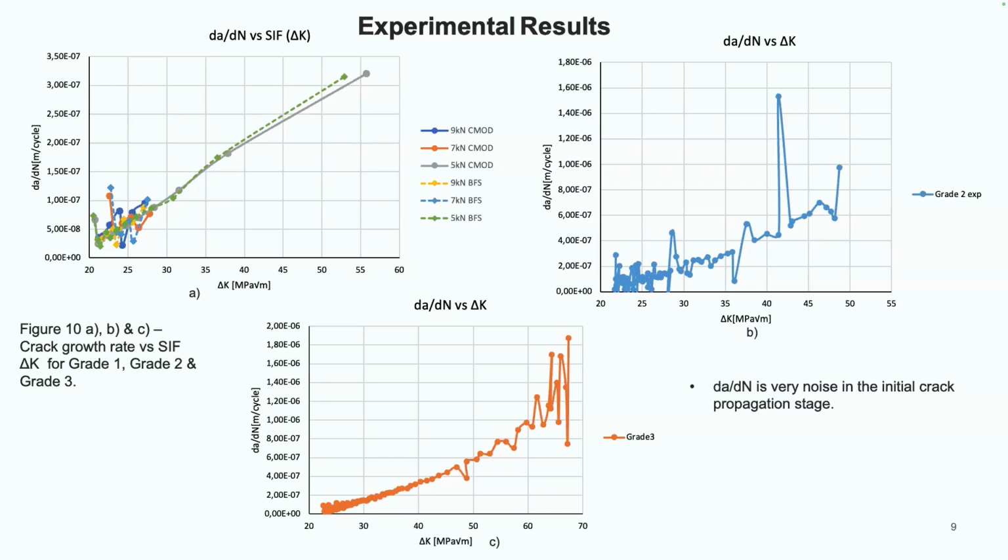One of the things which we thought might be environmental noise, so we are planning to use better shielded cables. And as I mentioned earlier, which was a quarter bridge kind of setup for the strain gauge, we'd probably use a half bridge setup, and hopefully we might get a nicer curve.